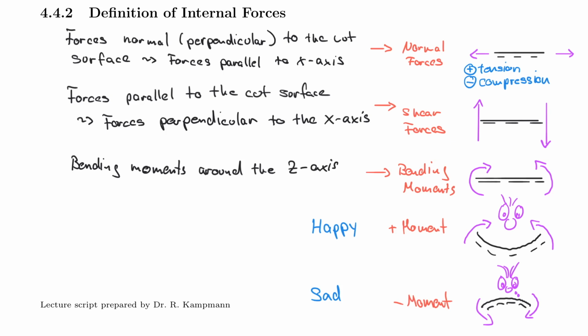But this takes us into the mathematical definition that I will define very clearly for you on the next page. For now, let's just understand that no matter if you have positive or negative values, everything has to be in equilibrium. So for example, here on the left side, you have a force that points to the left, therefore here it points to the right. So this element can be in equilibrium. Same thing here, you have a shear force that is going up and here it's going down, therefore the system can be in equilibrium. Of course this would rotate, but we have the moment as well that can prevent that, and if the moment is turning clockwise here, then it has to turn counterclockwise here. And by definition, you just have a positive moment when you have tension in the reference fiber, and a negative moment when you have compression in the reference fiber.